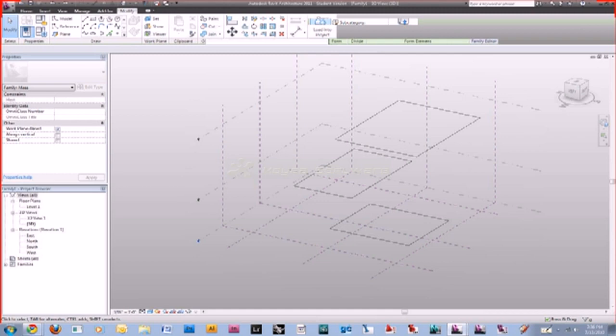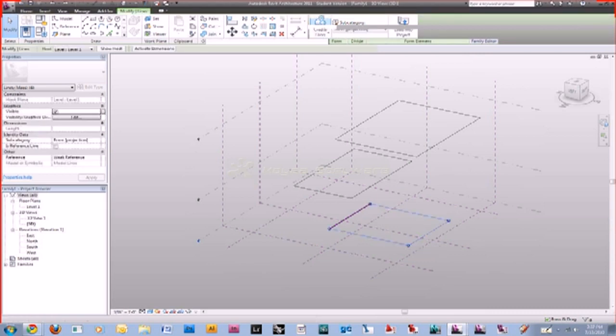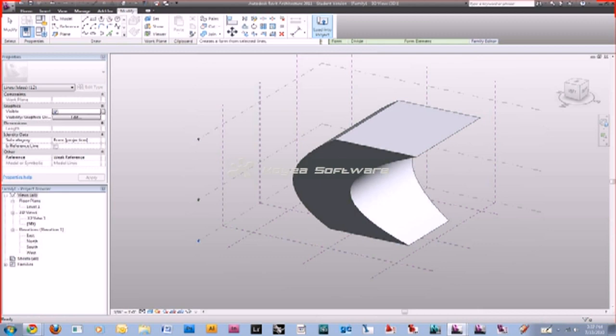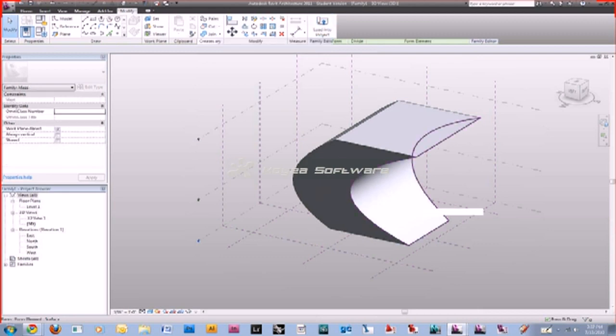There is a part of Revit where you do have to use buttons that have names instead of just creating arbitrary forms. But basically, with a loft, we're just saying that there's multiple layers. There are profiles that you're adding up to become one shape. That's what loft is. So there isn't a loft tool, just like there's not a sweep tool or an extrusion tool. There's only a Create Form tool.